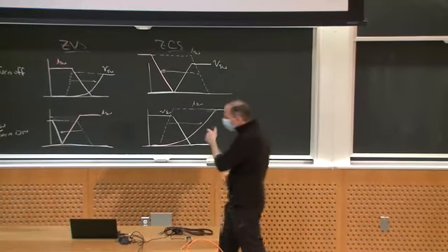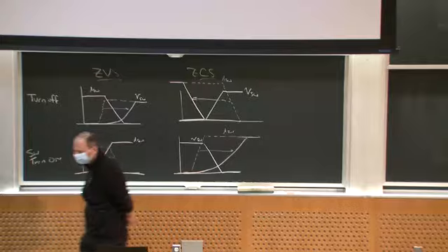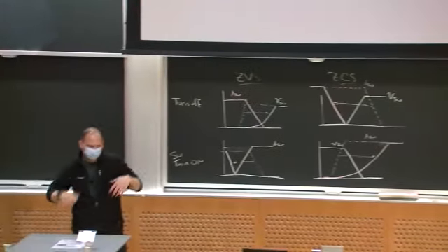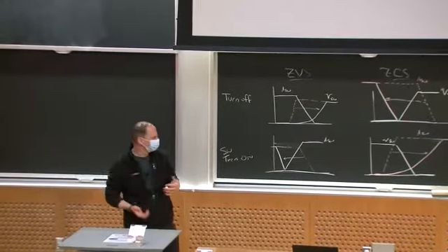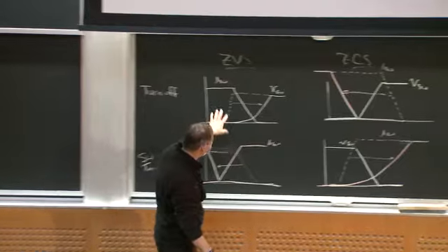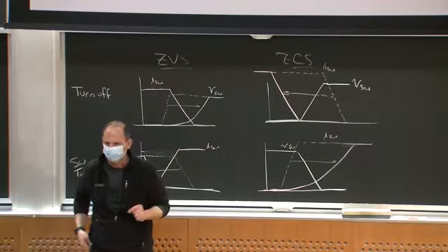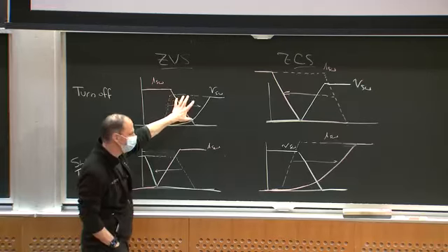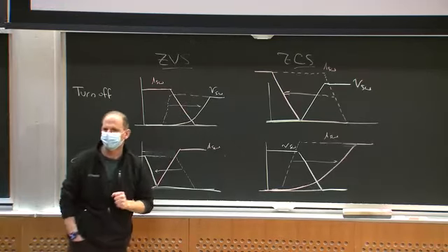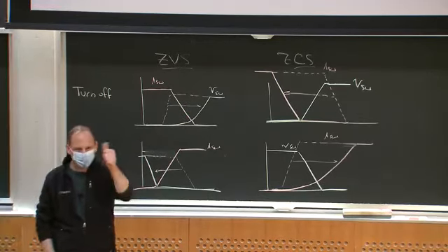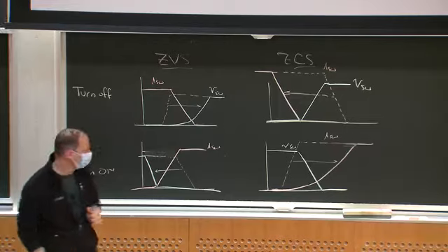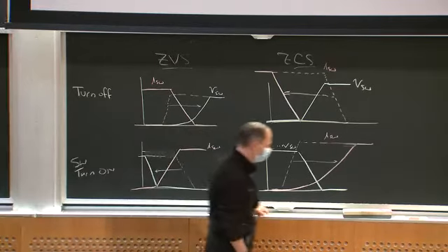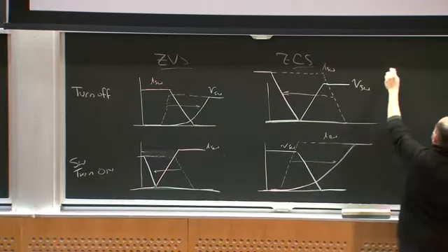Okay, so what do I get out of soft switching? Soft switching is sort of implied that if I'm snubbing the switch transition, I'm doing it in a pseudo-lossless fashion, meaning if I put a capacitor across the device for the turn-off loss, I'm going to recover that energy. So one thing I can get out of it is I reduce the switching loss.